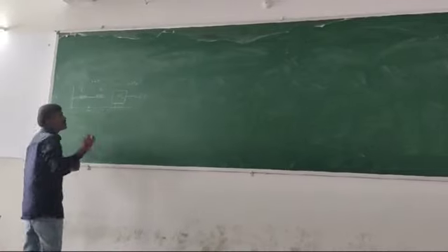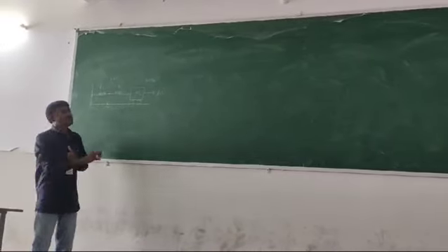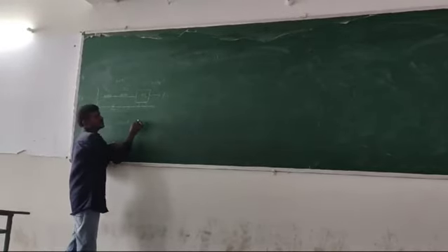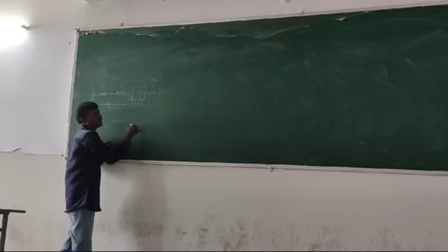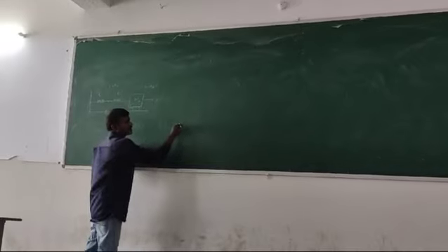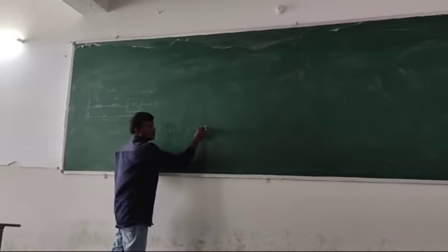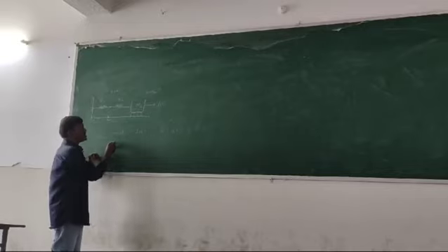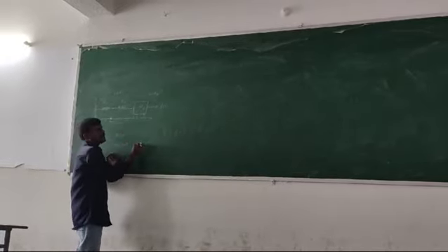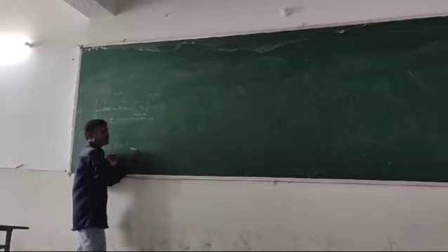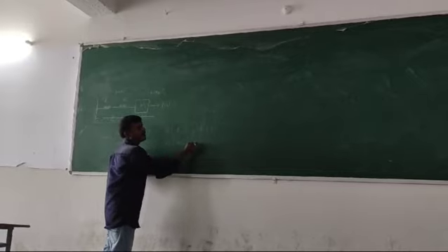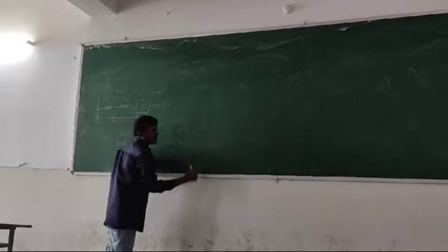So what are the inputs and outputs here? Input to the system is force, right? So Laplace transform of force is F(s), and output of the system is displacement, and I am considering the output as x2(t). So Laplace transform of x2(t) is X2(s).